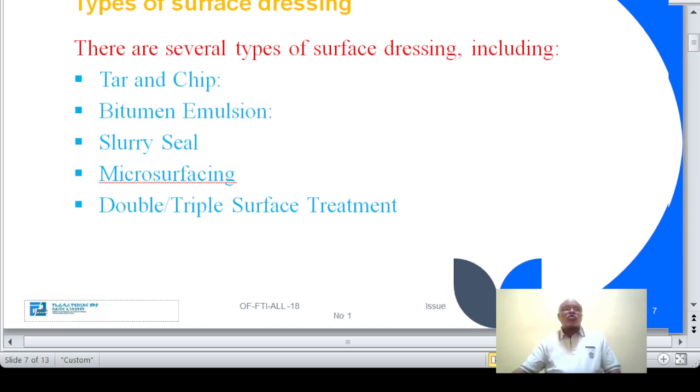The second one is pre-coating the chippings with a thin coating of hard bitumen such that the chippings do not stick together and can flow freely. Chippings which are pre-coated with bitumen enable the use of a harder grade of binder for construction, which can provide early strong adhesion and thus helps to obtain a high quality dressing.